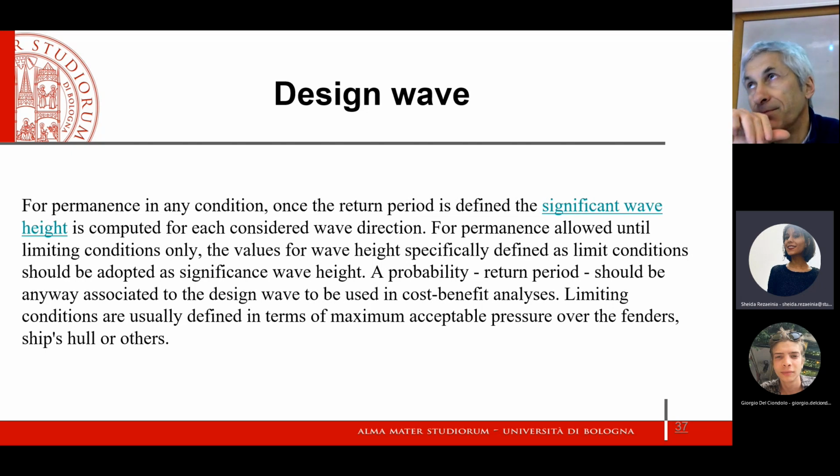Wave direction. Keep in mind that when you compute the wave height, like for wind, you refer to a wave direction. So we have to consider any wave direction, and in particular the wave directions that could be more impacting, for instance waves perpendicular to the berth.